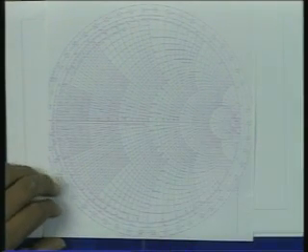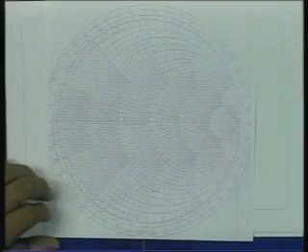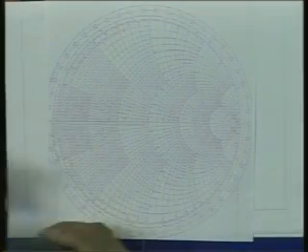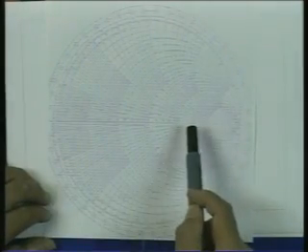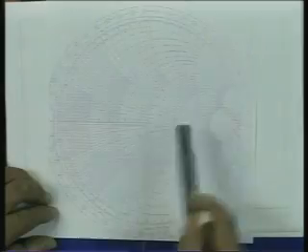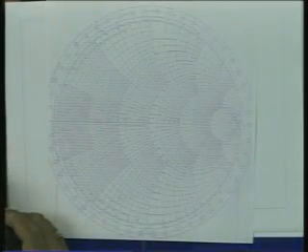However, we know that the impedance characteristics of a transmission line repeat every lambda by 2. That means, if I move by a distance of lambda by 2, I will see the same impedance. So, I do not get any advantage. Whatever impedance I am seeing, the impedance to be matched R, the same impedance now appears after a distance of lambda by 2. So, this possibility is not of any use, because it transforms the impedance to itself. So, the only possibility that I see a resistive impedance after transforming to a resistive value is that I move by a distance of lambda by 4.